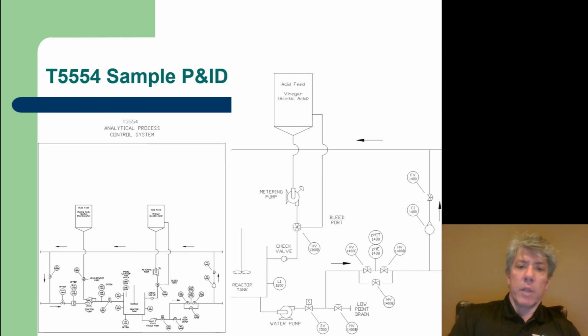But if we look generally at the right-hand side, the way I set this up was there was a reactor tank sort of in the middle of the system. You can see that shown here. It had a stirrer in it to make sure that the acid or base, in this case the acid that's being added, could be mixed in. And the goal of the acid was to neutralize what came into the reactor tank, because I made sure that something more alkaline, more basic, came into the tank and needed acid to even it out and come out to a neutral pH of 7.